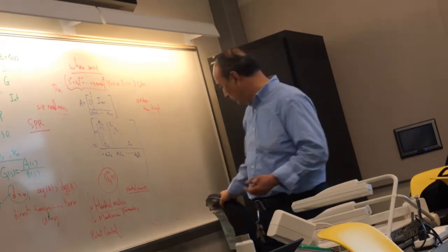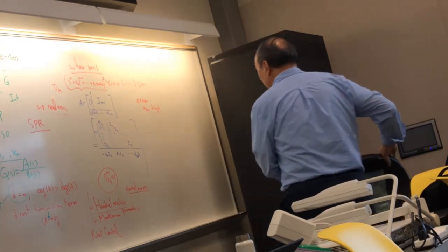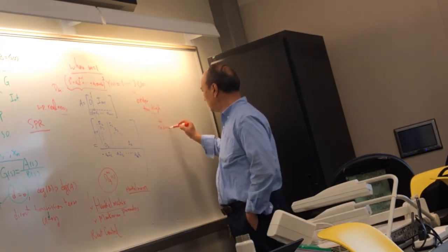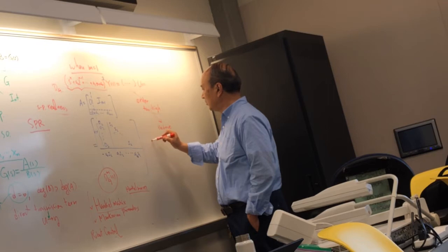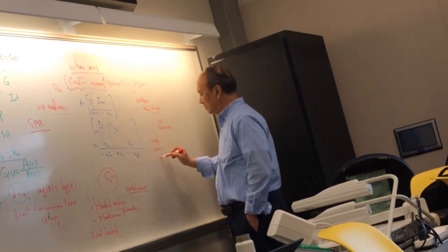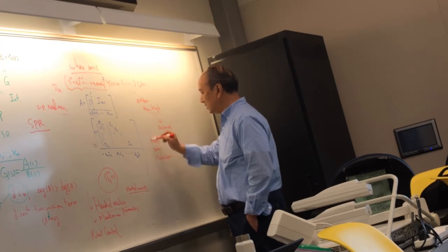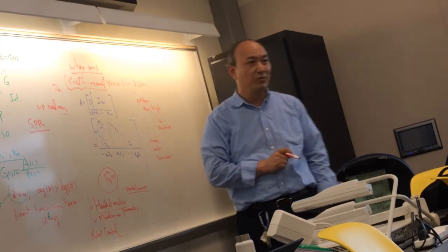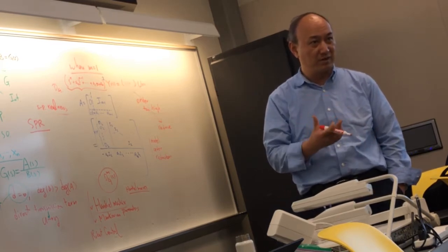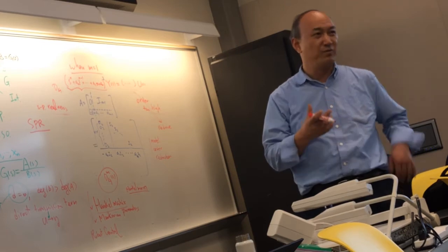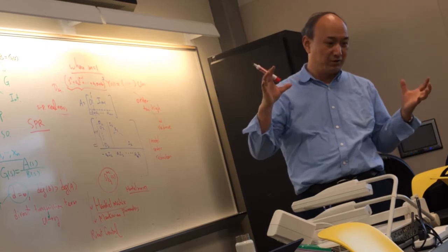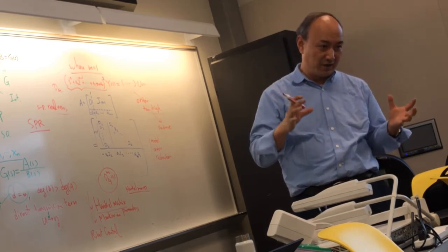So instead of working on a system model that is too high, can we reduce the order? That's called model order reduction. But when you reduce the order, you don't want to change the property of controllability and observability. You don't want to mess up that part.